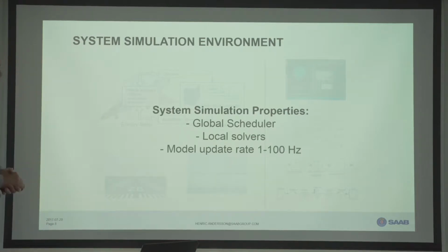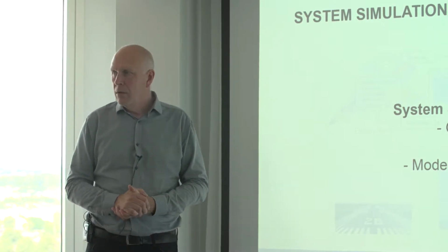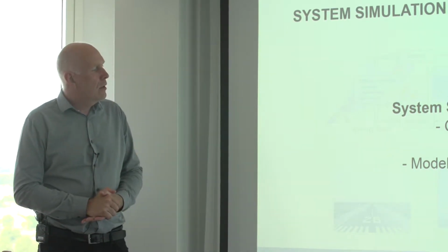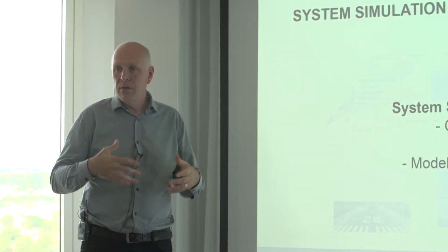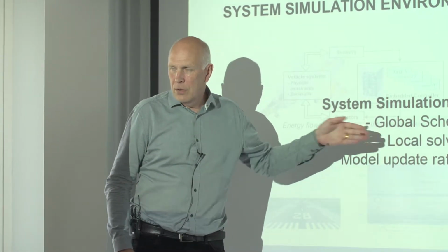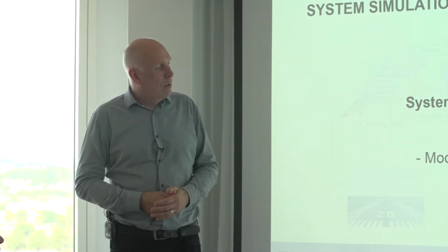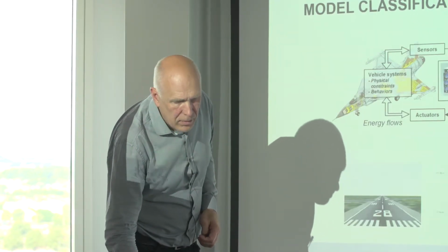In a typical simulator, the system simulator environment, our core is a global scheduler, but all the models' solvers are local. So it's not a global solver, it's local solvers. And the model update rate is between 1 and 100 hertz. Internally, it can be much higher for specific models, but on the global scale, they communicate at around 1 to 100 hertz. Just to get the feeling.